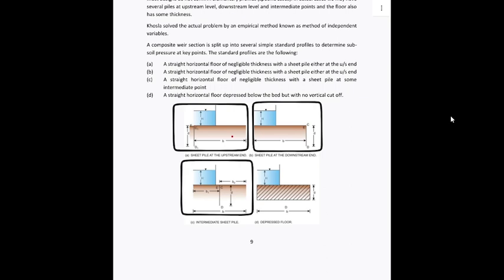As the water flows, remember it encounters friction, mechanical energy losses, and what have you, mostly due to friction, due to inhibition to flow, due to the permeability of the soil. So as the water flows downstream, you're going to have uplift pressures decreasing until you have zero. We expect zero uplift pressures as the water exits in the downstream part after the pile.